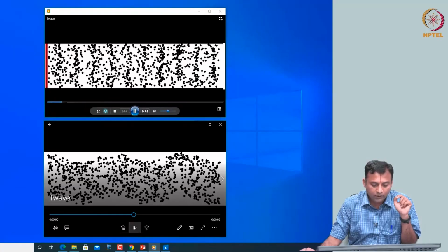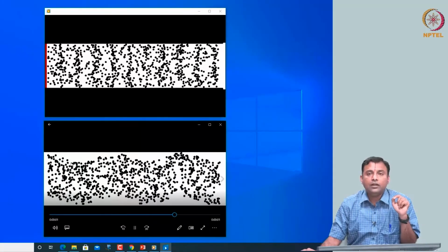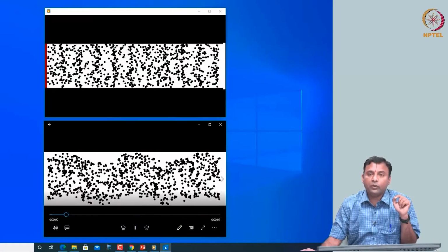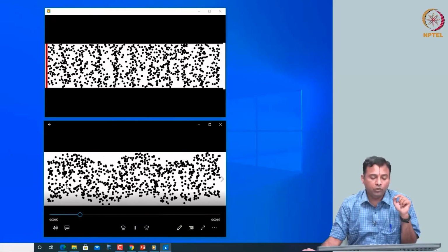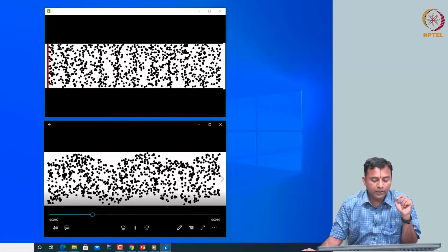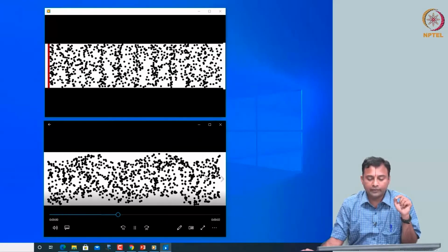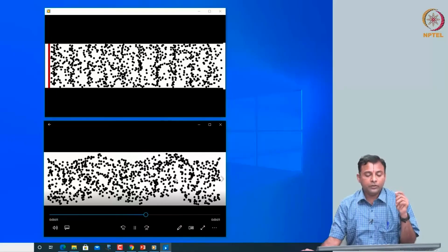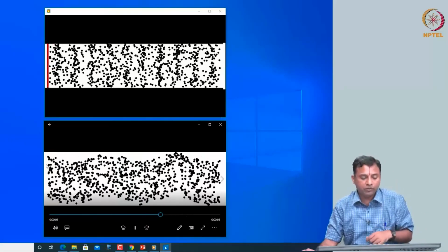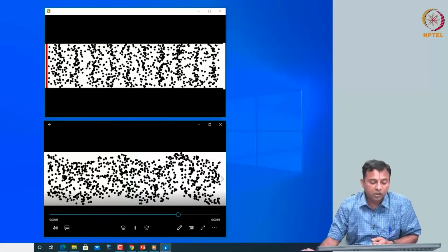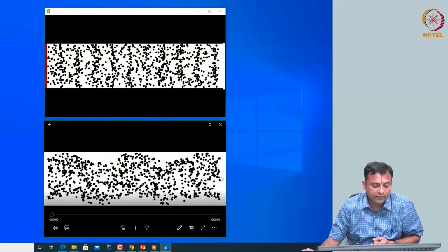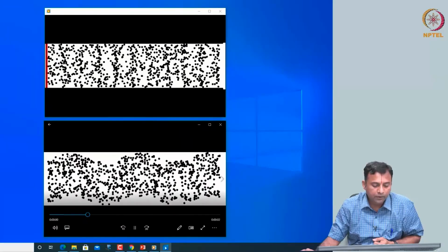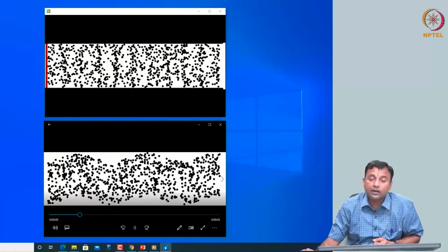Of course, the other one is your shear wave, the transverse shear wave. So why is it a transverse shear wave? Look at the particle motion. Clearly you can see a wave is going from left to right. But then you sit on this one particle, and it goes up, comes down, goes up, comes down, goes up, comes down.